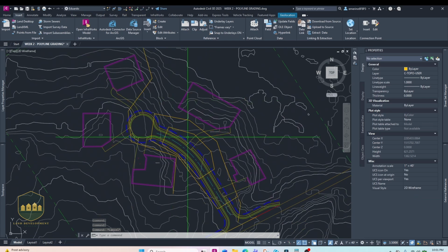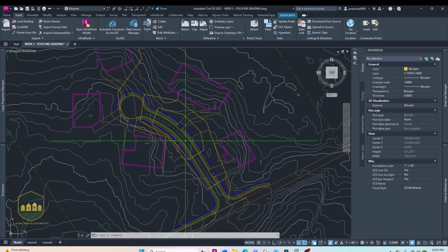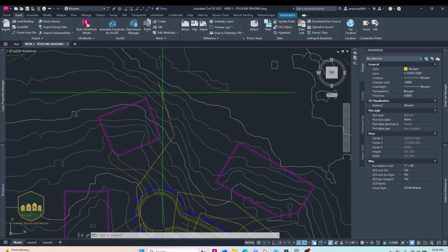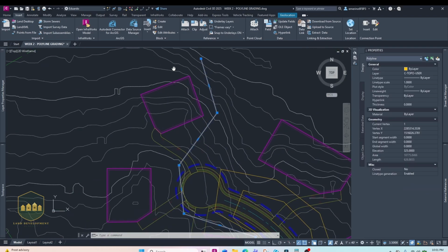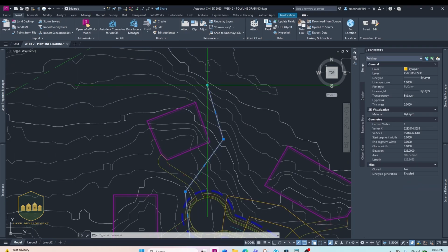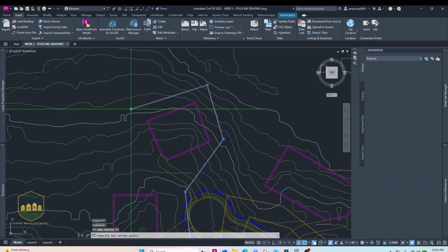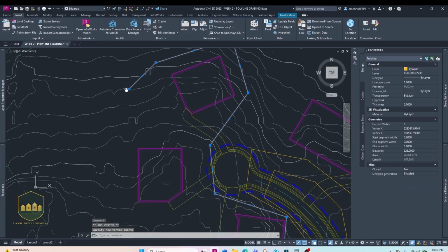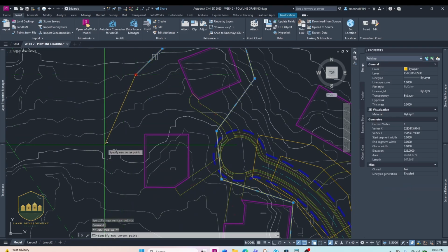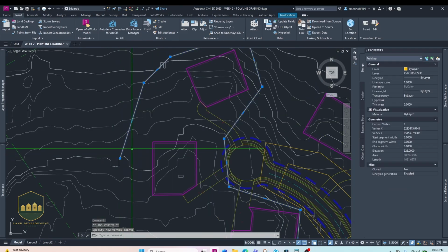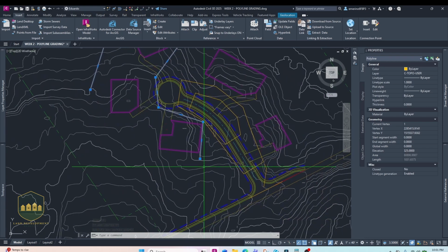So now I have my road graded in. The next step is I want to enclose my houses. So what that means is, again, I'm starting high to low. So I'm going to take this 325, reverse it, and I'm going to find that 325 existing contour, which is right here. This is 325. I'm tying it into the existing ground. And look at this.